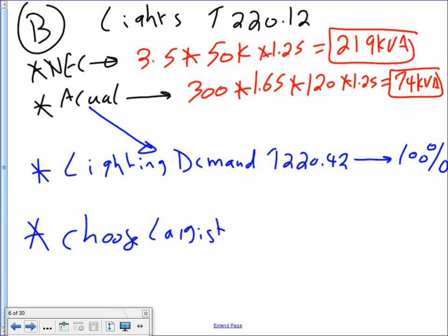First, you find the general from the NEC code book, and then you find the actual. Let me put the numbers on them. General light. This one will be 2 in your code, and total general lighting load will be 2.1. So this is 2.1 in your sheet. So important because it correlates to the sheet that you guys have.